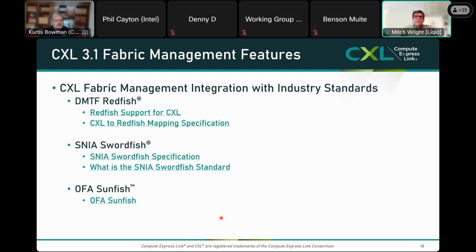Yeah, well, CXL fundamentally disaggregates memory out of the compute, which has been there for quite a while. And now we can scale memory along with compute and other resources such as accelerators. So once we disaggregate it out of the system, now we have a scalable bus, a scalable fabric that can add bandwidth and capacity. And we maintain the strong deterministic protocol and semantics of a memory bus. So that's very useful and powerful in a system.